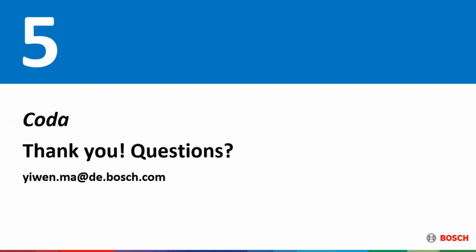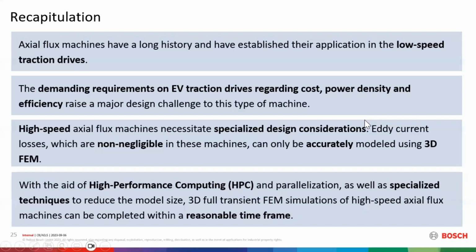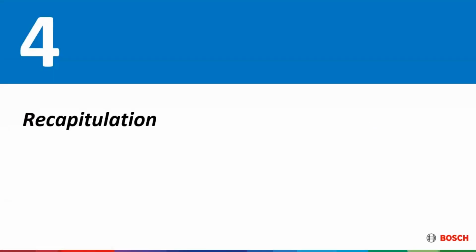I have drawn the meshes in the coils manually, directly in the geometry editor, and all other parts are generated in the designer with the built-in functions like size control. There are different functionalities in JMAG where you can specify automatic meshing. So it's kind of a hybrid. Only the coils I have done manually in the geometry editor using regular hexahedron meshes. Okay, thank you.